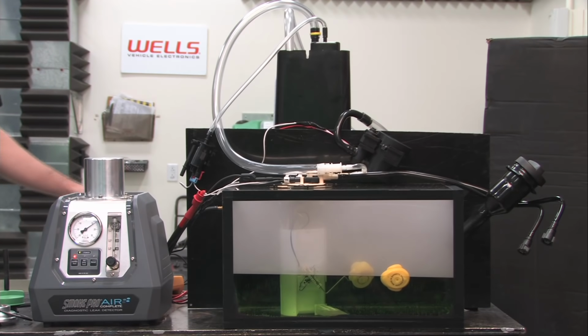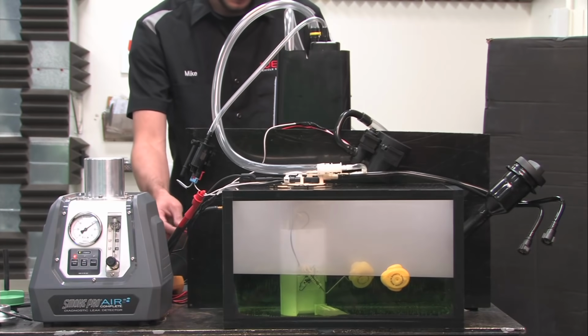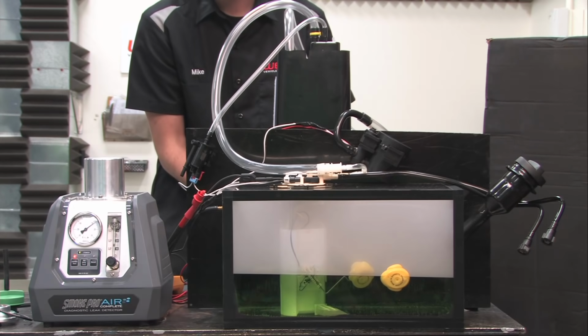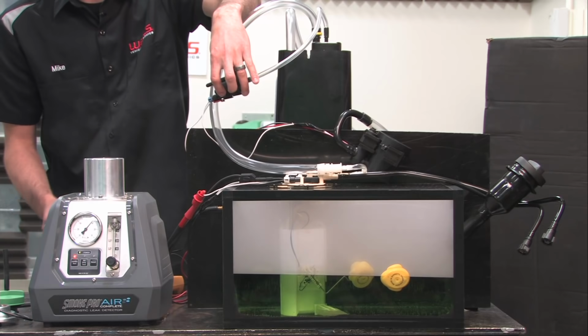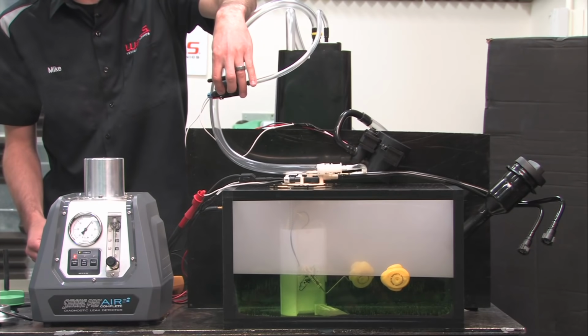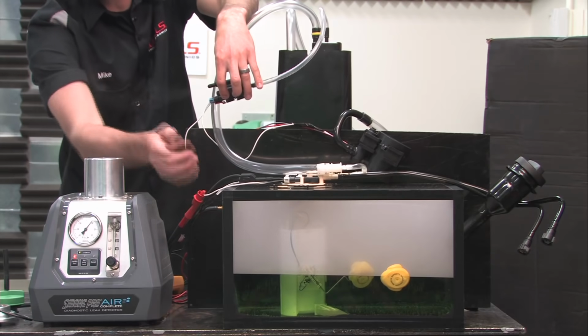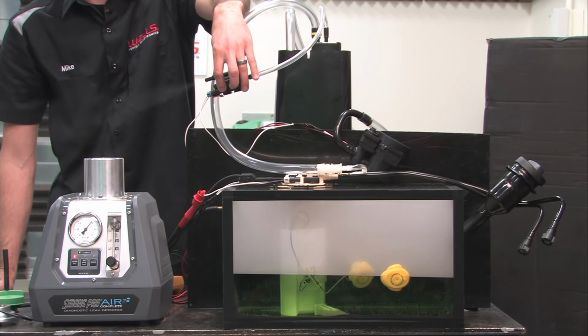And what I'm going to actually do now is open the purge, just like the engine were purging vapors out of this thing, okay? So we open the purge. I don't know if you guys could hear that pressure release, or can see this. There we go, you can see that. So now this would be just like the engine drawing vacuum on the system, drawing the vapors out of our tank, out of our canister, and into the engine to be burned. Okay?